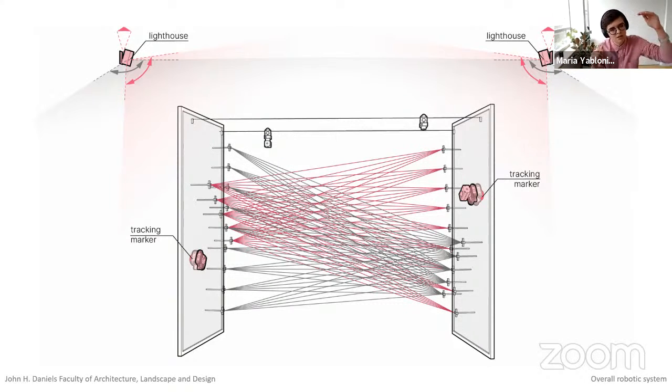In the previous case, there was a set of cameras looking at the robot body, and the robot body had a pair of visual markers on it. So as you fabricated more and more, you got more and more situations of obstruction of your visual markers, which made the fabrication process really difficult at later stages, especially when you had to attach your filament at the bottom of the anchoring curve. Here, because of the sandwich kind of topology of this robot, I could attach the tracking markers on the outside of my work envelope, because I'm operating on these thin sheets of plastic that are suspended in the space. So my tracking system is outside of the workspace, minimizing the problem of obstructing the actual marker within the fabrication space.